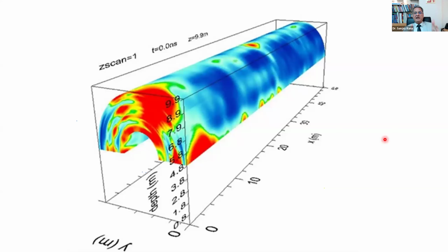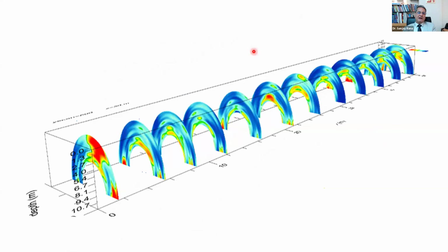And at the end of it, we'll create a model like this. So this is the tunnel, and this is ground beyond the tunnel. Wherever you have any problem in terms of cavities or delamination, you will have your red hotspots, as we call them, high reflections, and you'll be able to get it. You can again cut it in slices at different chainages, see how the zone is going from one part to the other. Very strong method, simple GPR, based on different frequencies, but you can model the entire tunnel in 3 dimensions.